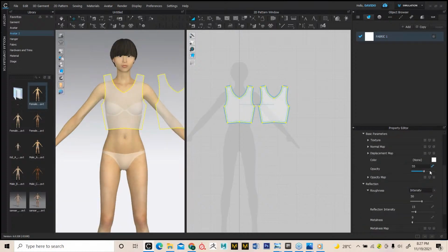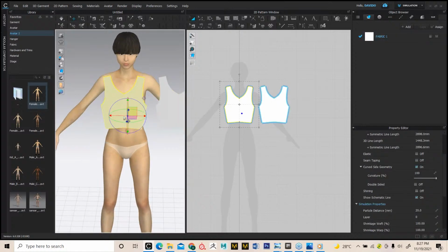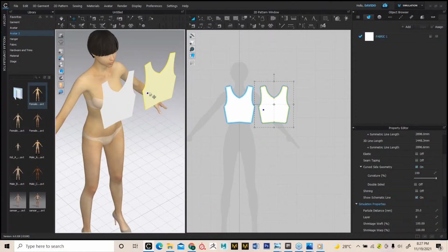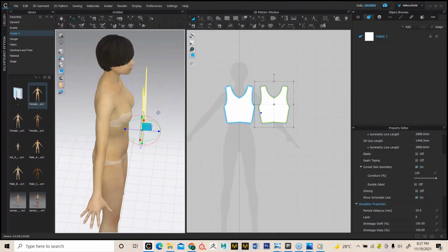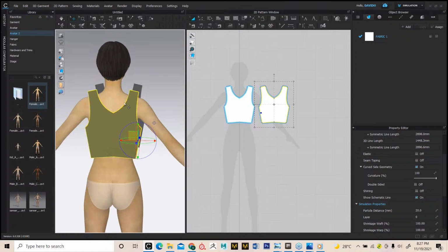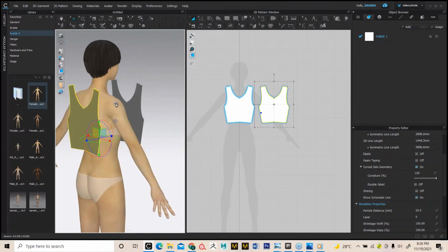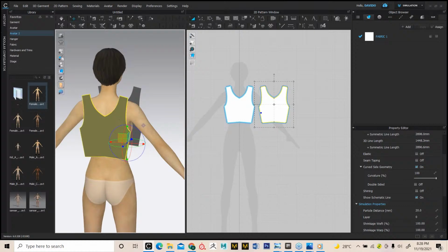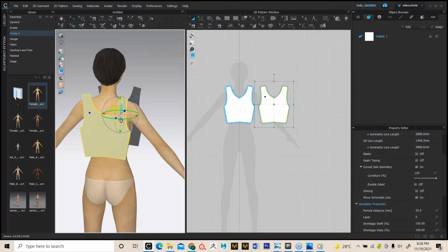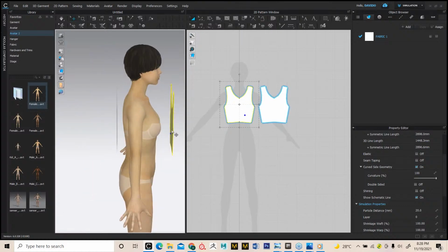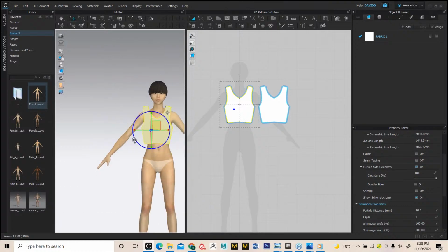Well, the first step you need to take is to position your clothing material in the right place. You can do this manually by selecting your object that has already been created in the 2D and moving it to the side you want to sew it on the avatar's body. Then another thing is that you have to flip it horizontally, because you don't sew the back of the clothes to the clothes. You have to flip it first. To flip, you simply right click and select flip horizontally so that the back side is facing inside. Then we can move this a little bit too. All right.